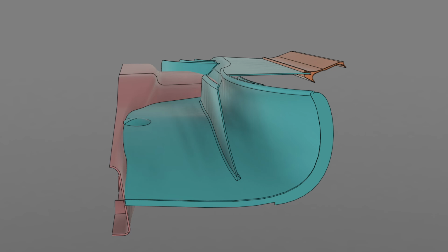You can see the venturi tunnels don't come all the way to the bottom of the floor, even at the throat. I did this on purpose to lessen the aero sensitivity of the floor. The ratio between the cross-sectional area of the throat and the outlet of the diffuser is called the diffuser's expansion